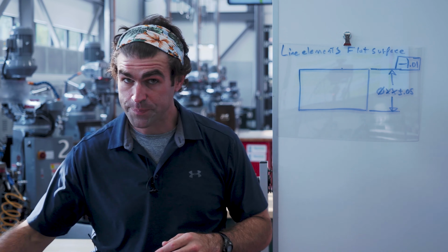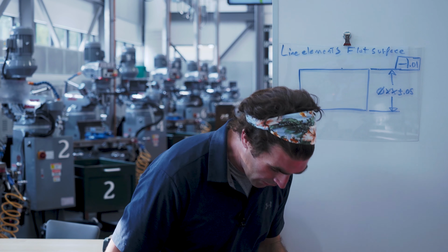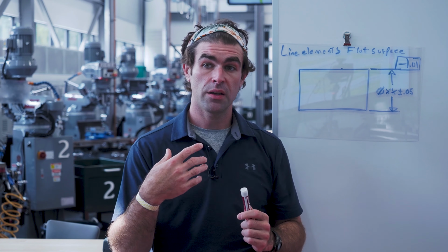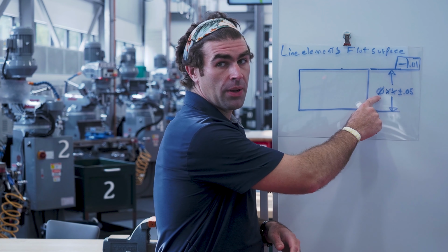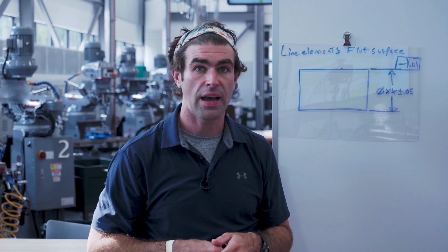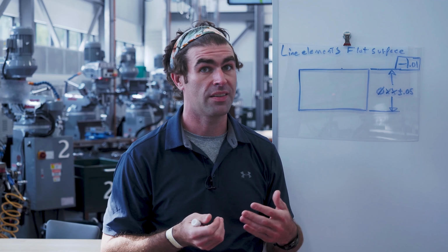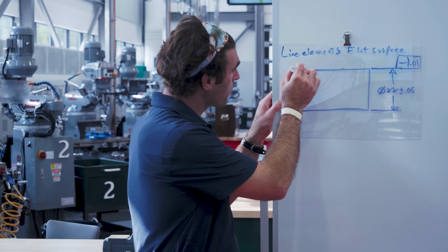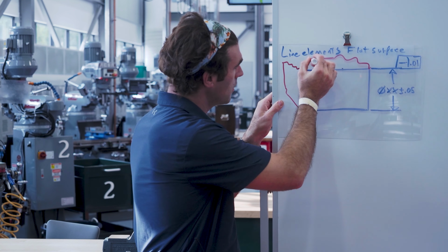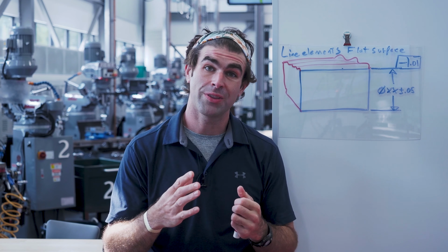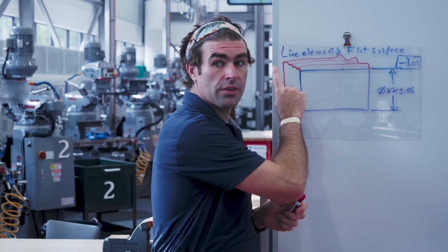So what that means, on a part like this, say it's a rectangle, right? If we went to go inspect this, right, we check for size right here. It doesn't matter what this is, but say we have 50 thou, so 100 thou of total tolerance. We have the straightness that tightens it up a good bit, 10 thou. But if we draw this part in 3D, right, I'm going to just bring it out. We only need elements to be straight within 10 thou going in this direction.